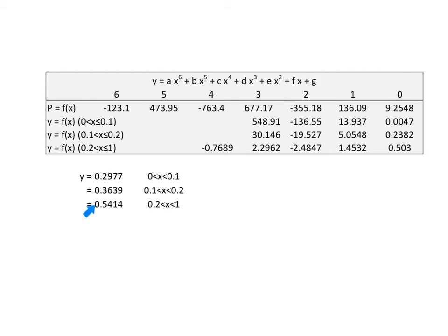Now, what I do is calculate, based on whatever is the liquid phase composition, the vapor phase composition using all 3 different equations. And I'll use a logical statement in my Excel spreadsheet to select which one of these to use for the vapor phase mole fraction.